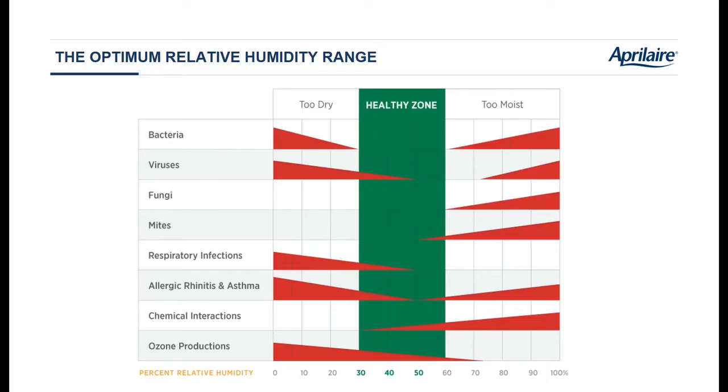Don't sell the dehumidifier on the promise that you're going to be able to maintain 40%. That's going to have to be a very, very, very tight house. And even then, you're going to make the dehumidifier run a lot. The important thing I want you to focus in on is what have we gained by going from less than 50% down to 40%? We've gained nothing.